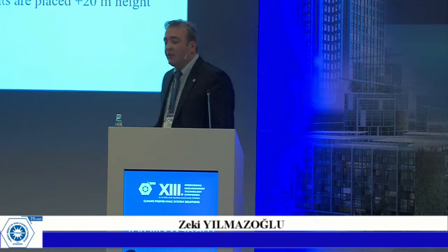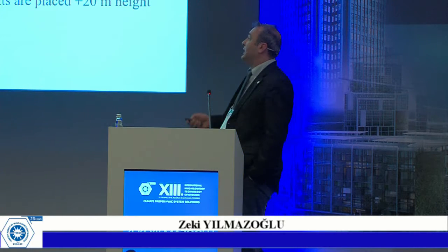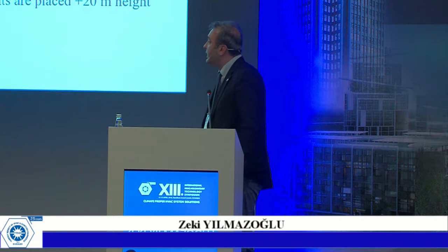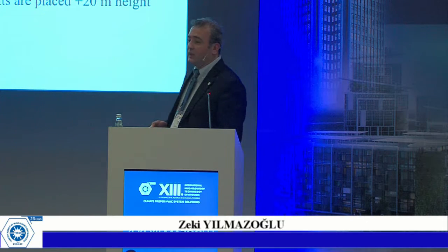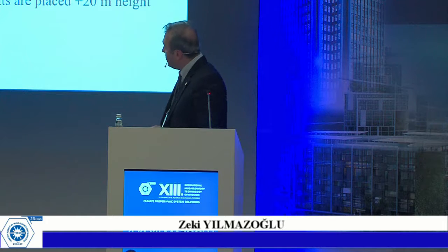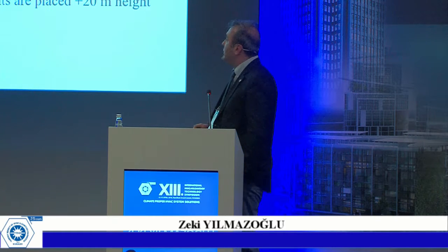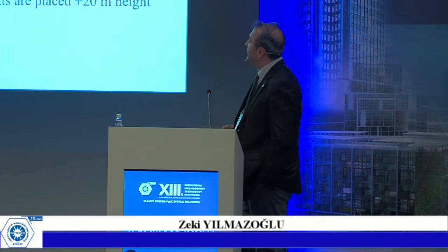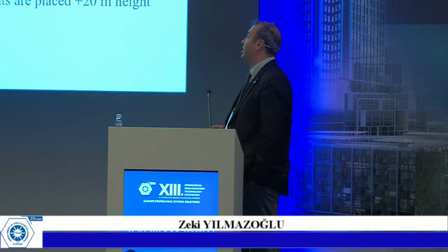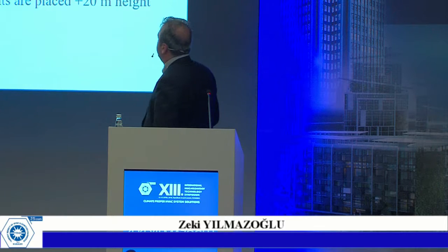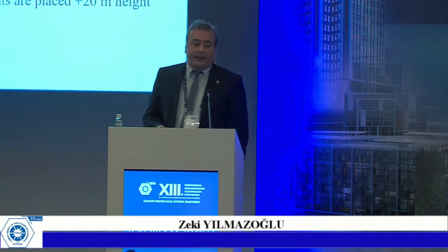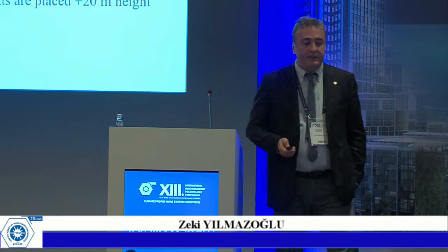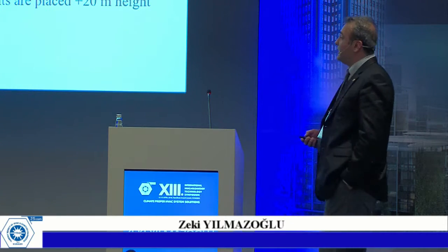We have two cases. In case 1, or case A, the trigeneration system is located close to the high-rise building, maintaining existing buildings on the island. For case B, the buildings that are not to be used after construction of the other high-rise hospital building are pulled down, and the energy island is located further away from the new hospital building. Fresh air intake apertures of the air handling units are placed at plus 20-meter height of the building on the leeward side.